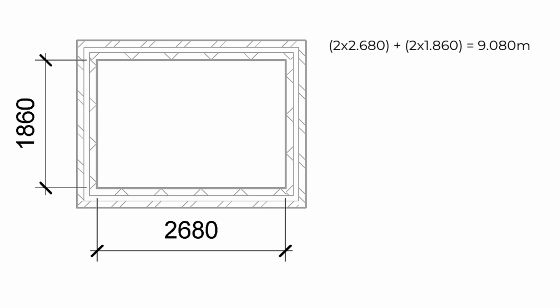What we are required to calculate now is the distance all the way around the centre line of the blockwork, the cavity, and finally the outer brickwork skin. Let's examine the drawing. The green line is the distance around the inside of the room, referred to as the inner girth, which we have just calculated.